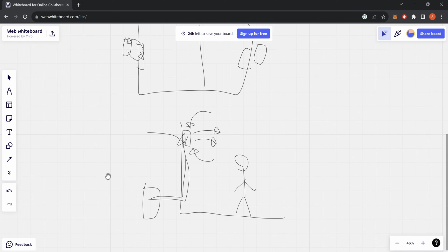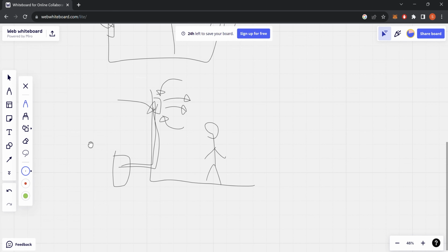And we'll talk a little bit about that in the PowerPoint in the future. But for now, you need to understand that ductless units, this is what I'm referring to. They are ductless because there are no ducts. Okay. A central system has one fan, many ducts to flow that air out into the house. But a ductless system would have individual units in multiple rooms where it's just mixing the air in that room. Okay. So you'd rely on basically this and or natural ventilation of the house and or windows that can open and ventilate the house.